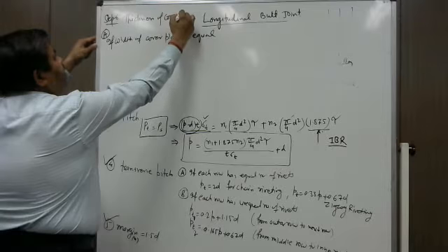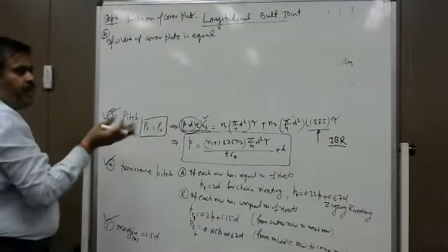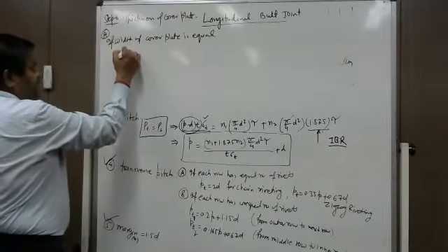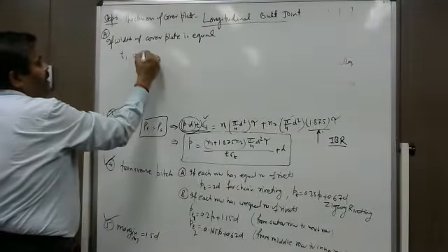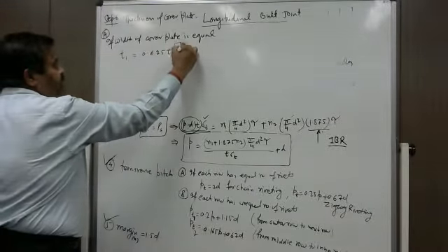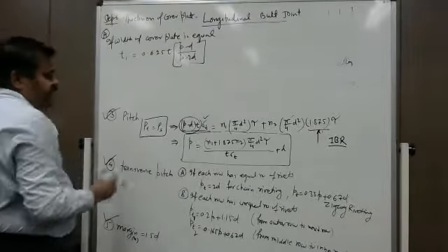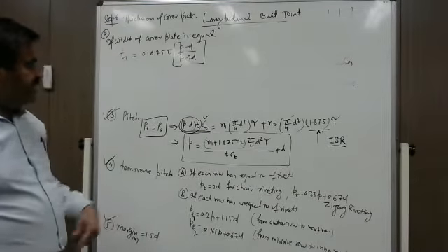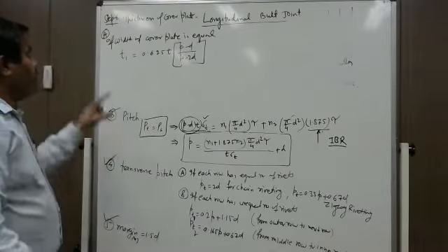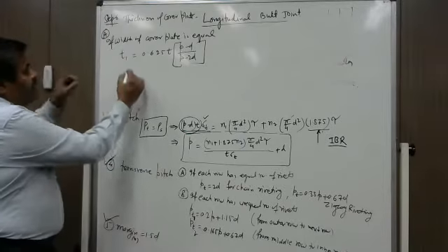Again there are two cases. When the width of the cover plate is equal for the top cover plate and bottom cover plate, then the thickness t1 is given by 0.625 t (p minus d) divided by (p minus 2d). These formulas, whether for the transverse pitch or otherwise, are all given in the data book, so there is no need to memorize them.